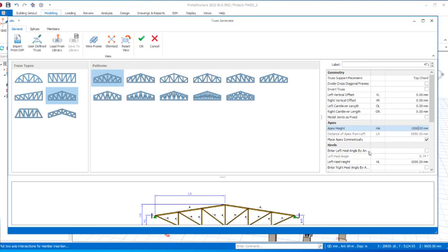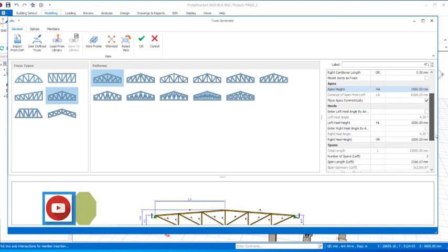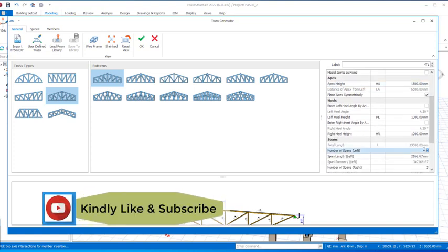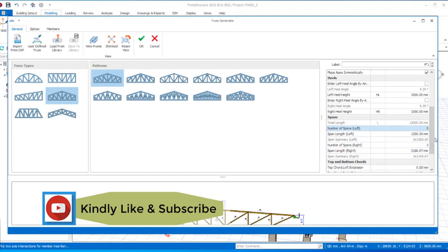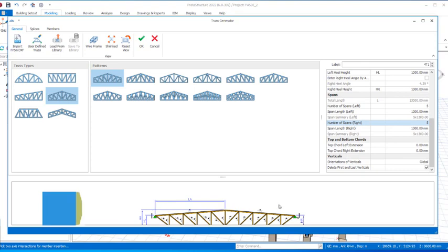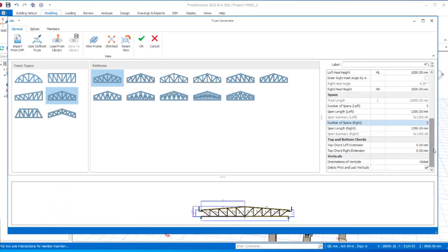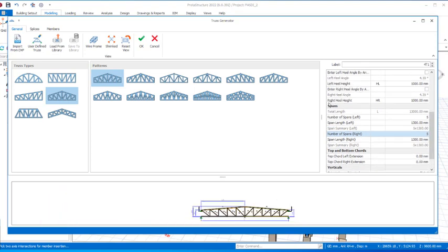So we have to also scroll down to the spans. The span is 3, we make it 5 in that provision, and then this other provision also 5. All right, so we have something of this kind. Then for the right here height, we will change that to 700, just like this. Also the left here height, we also change it to 700, just like this.